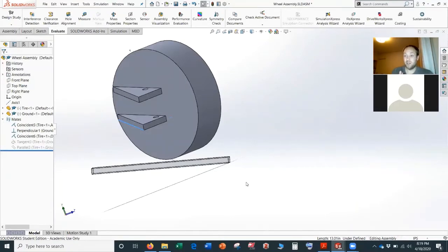There are some additional effects that this kind of messes up your weight shift in the rear, though. So we'll show a little bit more about that later. And this is better than, for example, the kingpin inclination, right? We noticed that it lifted our CG up as we turned, which isn't great in a turn. So this caster with a little bit of scrub radius really helps put that weight down on the front right tire.